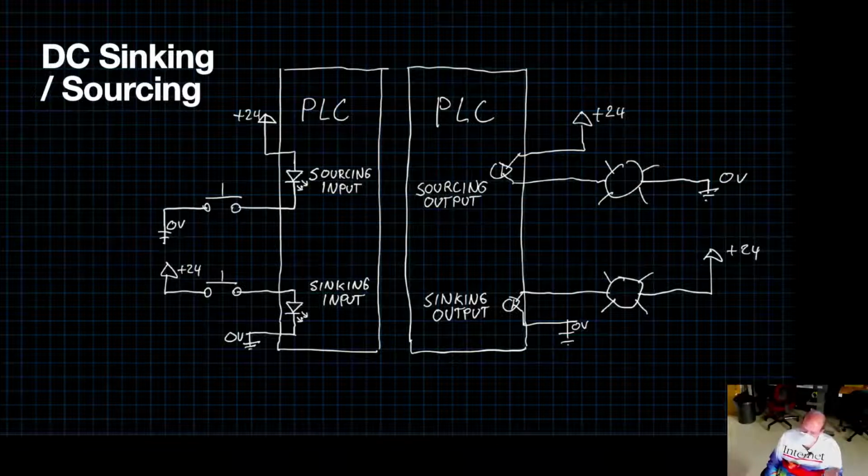One of the reasons I'm explaining sourcing and sinking outputs here, so like making such a big point of it, is because if you're connecting something else to your PLC, so in the motion case is the case that I am more familiar with, where you're wiring a stepper drive or a servo drive to the high-speed outputs on your PLC, you need to be aware of what direction those expect you to pull the pins to make them active. And when working with stepper drives, they expect their pins are being pulled up internally, and then your PLC will pull them to ground, which is not the way you would typically think about, like, I'm turning on a light, is by pulling the light to ground, which is why you need to be aware of them early enough in the process that you're buying the correct module for your PLC.